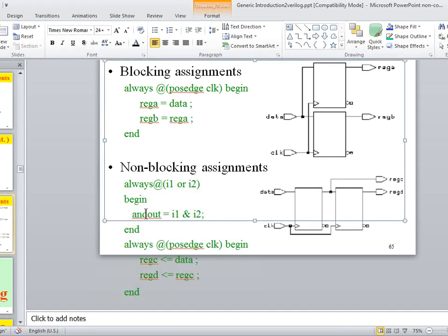For bigger designs, I have to end up using this AND output in the same always block as the sequential logic. In such cases, I can use blocking everywhere or non-blocking everywhere. I cannot use blocking for sequential logic. We saw the reason for that. So I have to end up using non-blocking for my combinational circuit also, which will work okay. It's not an issue.